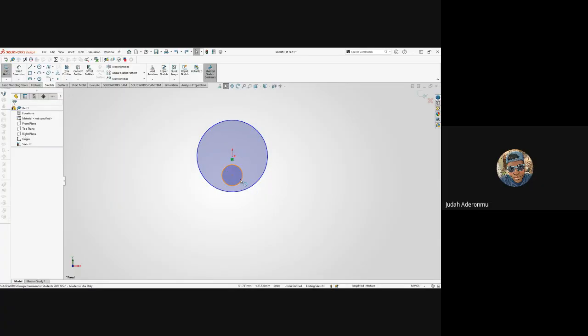And now for the final one. Let's say I have this circle here, and let's say I don't have this origin. Because now you have an origin, I can easily use it to pin to the center. Let's say I don't have the origin. Let's say this circle is just something I randomly created in my sketch, and I want them to share the same center. All I have to do is click on one circle, hold down Control, click on the other, and set it to be concentric.